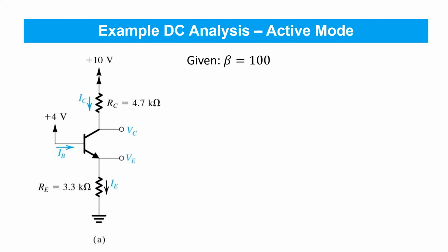As usual, the analysis of electronic circuits is best learned by practice, so we'll go through a couple of examples here to illustrate the principles at play. Here's a simple schematic where all voltages and currents are DC quantities. There's nothing time varying here, so we denote the resulting currents and voltages with uppercase symbols and uppercase subscripts. Remember, that's our notation for DC quantities. And we're asked to find the collector voltage and the emitter voltage with this NPN transistor and resistors in place.